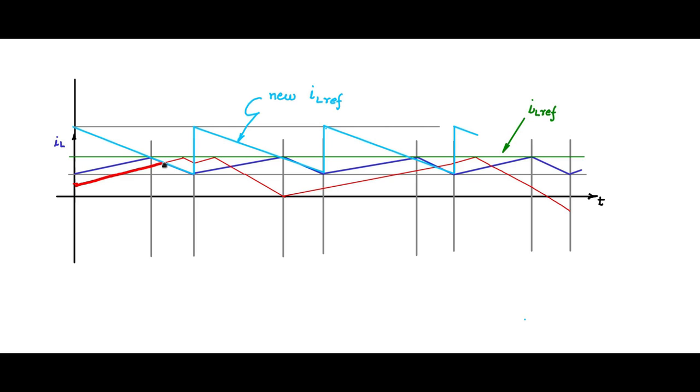So thereby it will then start having a downslope, and the downslope is going to be along the same parallel, because the falling slope for the inductor current is minus V naught by L, or minus VB by L in this case. So you see that in just one switching cycle, the error has been reduced. From there on it continues to follow the steady state value.